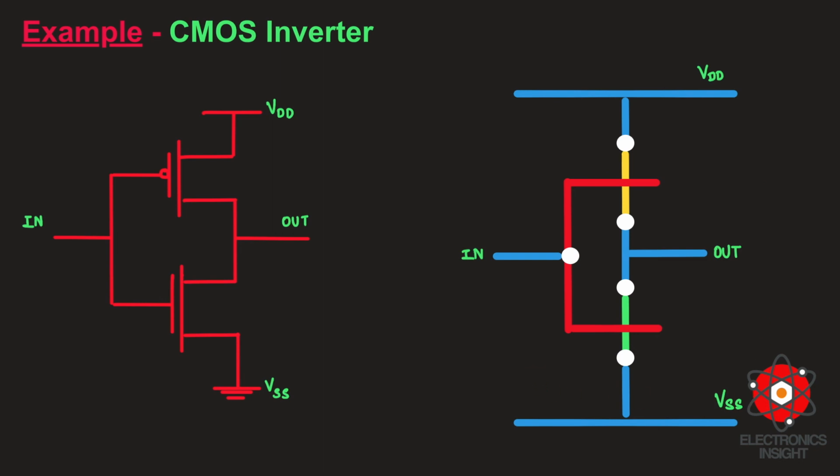To summarize the first part of the video on stick diagrams, we have understood clearly how to represent a stick diagram for a basic CMOS inverter. That is the first point. And before that, to draw that particular stick diagram, we have understood certain rules, and we have seen all the design rules step by step, and we have also seen the color codes to represent all the layer information that is hidden in the schematic diagram. So a stick diagram is basically a cartoon of a layout.